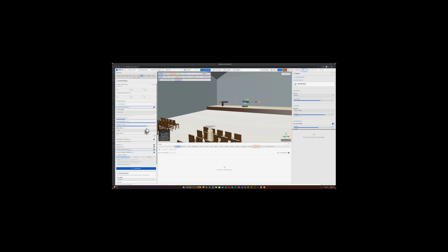Turn on the radiosity solver, which can improve realism and stability in many scenes by better accounting for diffuse energy exchange. Next, enable the FDTD wave simulation to improve accuracy in the modal region, especially below the Schroeder frequency, where discrete room resonances dominate. For this particular example, we won't enable ray transmission, since that feature is most useful when modeling sound passing between adjoining spaces.